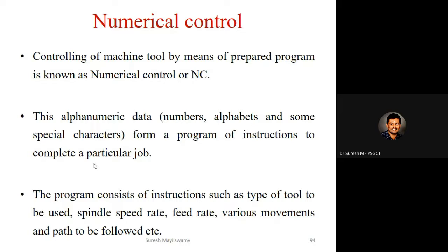A numerical control system is a system in which actions are controlled by the direct insertion of numerical data at some point. The system must automatically interpret at least some portion of this data, and then only will it react to the CNC program. The controller gets the CNC part program and converts it into machine language, which is zeros and ones, so that the actuator will do the machining operations.